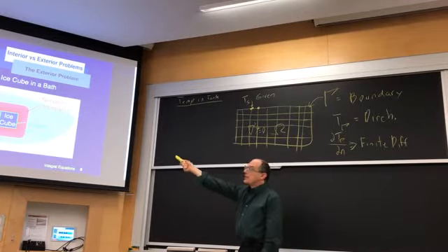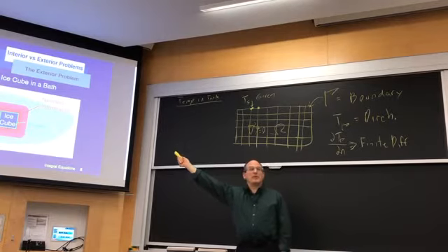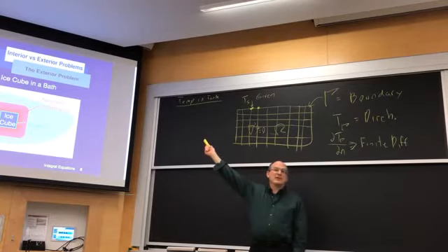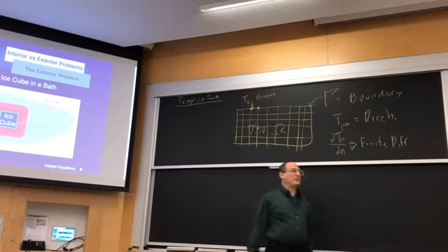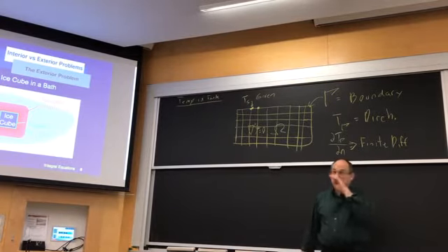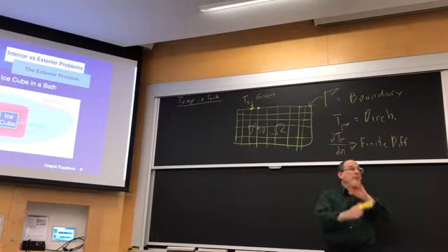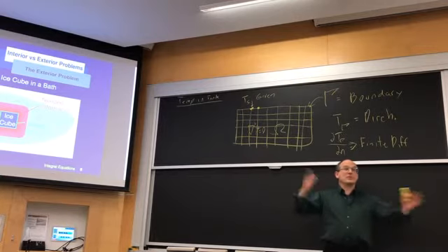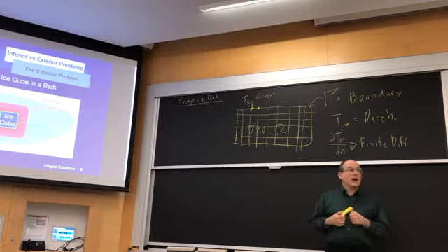We can do it by solving the exterior problem. But the exterior problem is infinite in extent. How do we stop the mesh? At what point do we, since obviously we can't fill all of the infinity with a finite difference mesh, what do we do instead? So I have an ice cube. I know what its temperature is. It's sitting in the ocean, which has a given thermal conductivity. And I want to know how fast the heat's leaving the ice cube. How do I answer that question with finite difference methods?